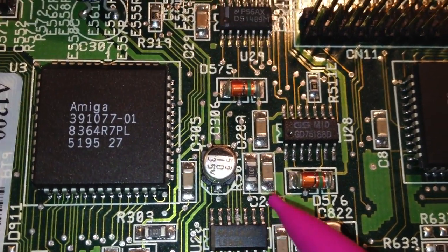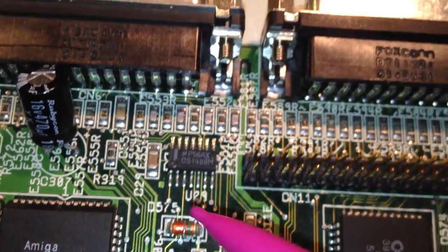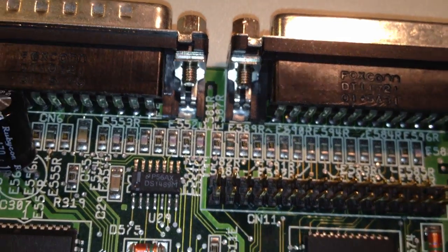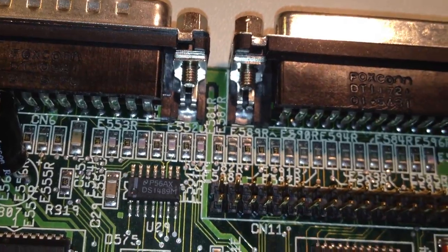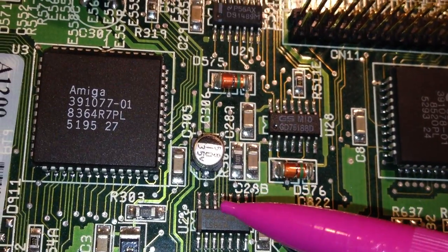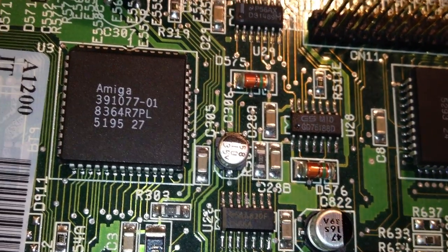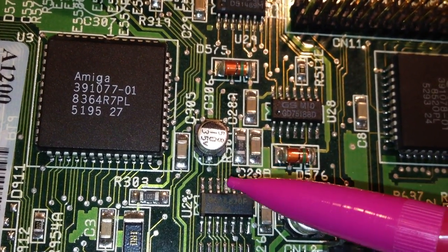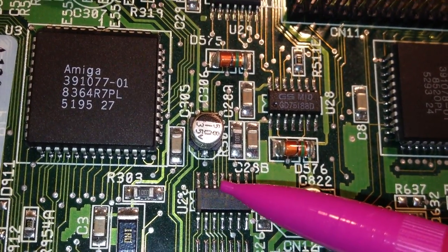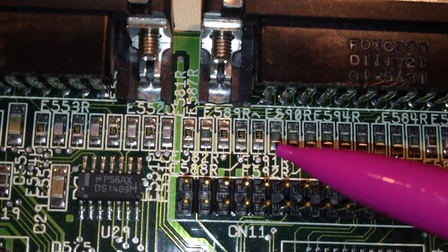But if you don't get any reading at all, then there might be a break in the trace on the motherboard, or there might be something wrong with this resistor. So you can just use your multimeter and find out. If there is a break in the trace, then you can jumper wire this point here. It's kind of small, but if you use a soldering iron with a really fine tip, then it's possible to do it, and use a really fine wire, not a thick wire. So you can jumper wire this point then to the bottom side here of the resistor.